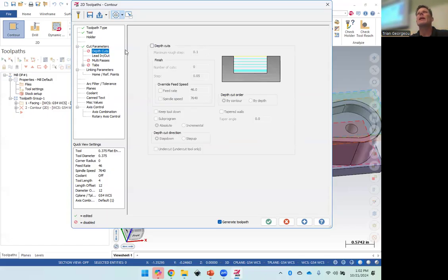Should we do depths of cut on a 3/4 inch depth and a 3/8 end mill? We'll do that. We'll do it in 3. We'll go 1/4 inch depths of cut. We don't want any finishing passes. This is on the floor. Does everybody understand this depth of cut is the floor for the finishing pass? It all makes sense if you sit there and look at what it says.